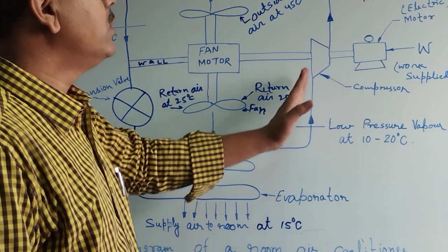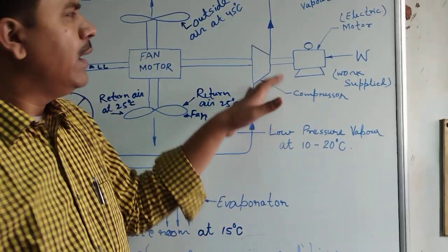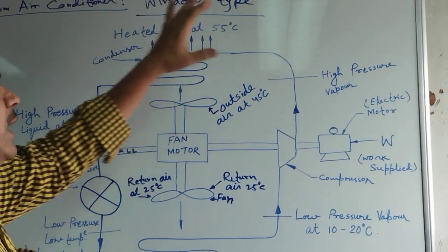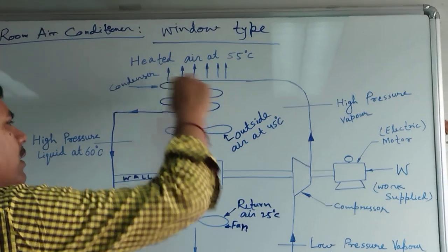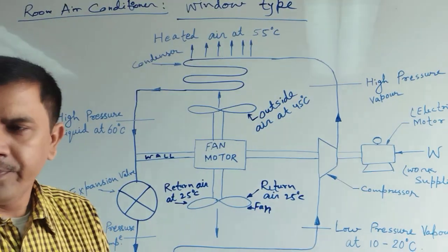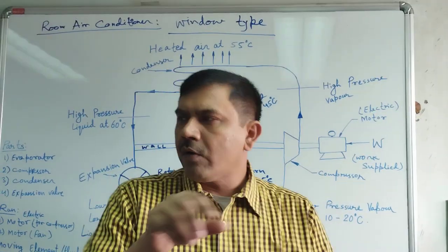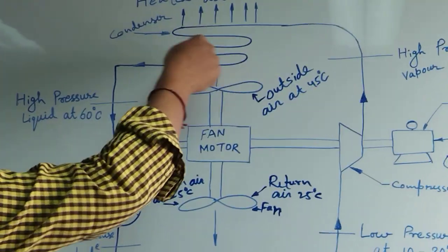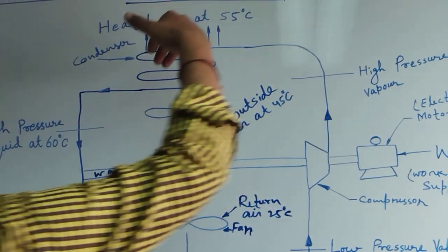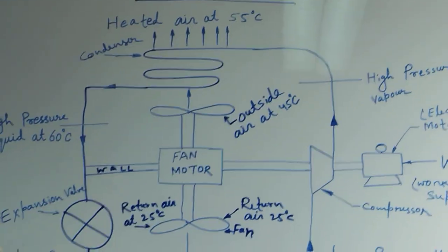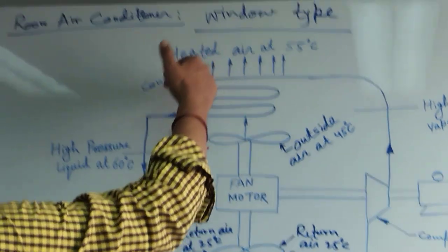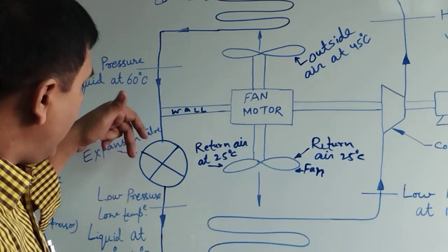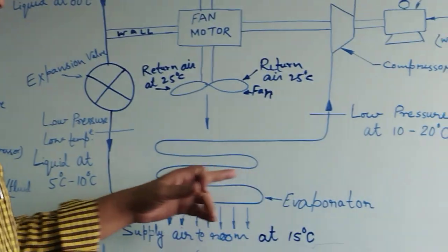It will go through the compressor, another part, then the refrigerant goes to the condenser. This is also a fins type, and the fins are cooling the environment. The fins are also combined together. Then when the compressor is exposed to the air in the outside environment, the refrigerant comes to the expansion valve, and after passing through the expansion valve it will go through the evaporator.